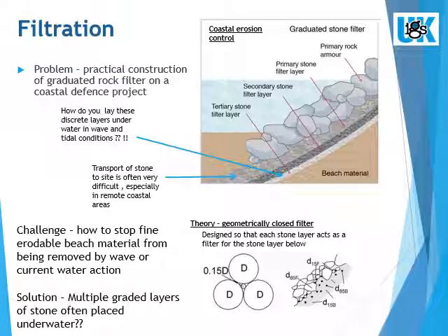One answer is to use a similar idea to the Terzaghi filter, where progressively bigger stones in a series of layers are placed in succession to prevent the layers below migrating out to the surface. Well, this works in theory, but it is very expensive and in some instances virtually impossible to construct, especially below water.